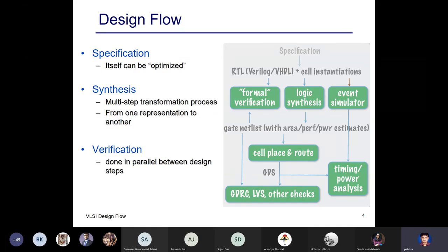So how do you do synthesis? For this Verilog, we will use today a free Verilog simulator called iVerilog. We'll have two steps. First, we'll compile the description language to see that it's syntactically correct. And then we'll have a.out. This a.out we give to the simulator, and the simulator will simulate the input and output. For a given input, it will simulate the output.